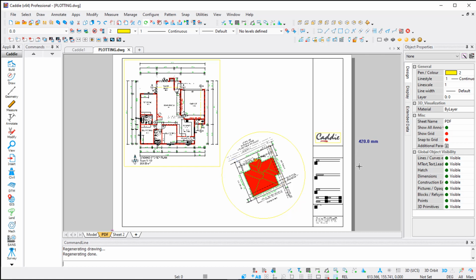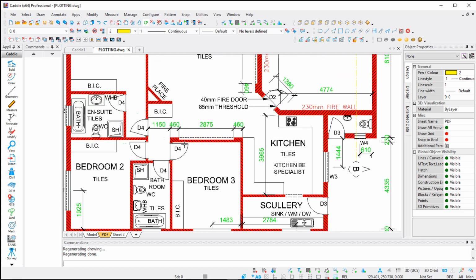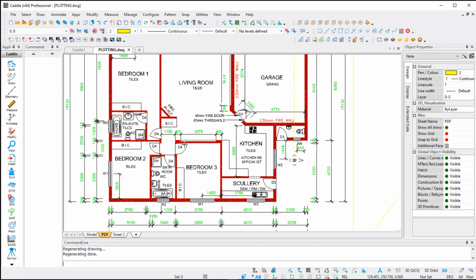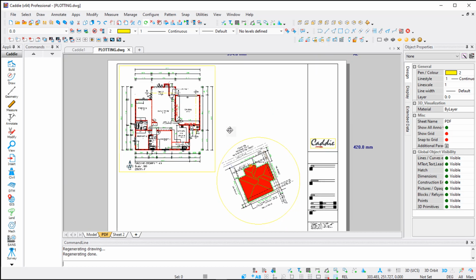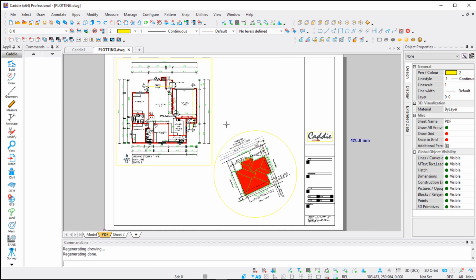Now you've managed with your title block and your viewports, so now we want to send it down to your printer. As you can see, I made use of different colors: green, black, red, as well as some yellow. The first exercise is going to start off with creating a mono plot style, so regardless of what color I've used, everything will print black.